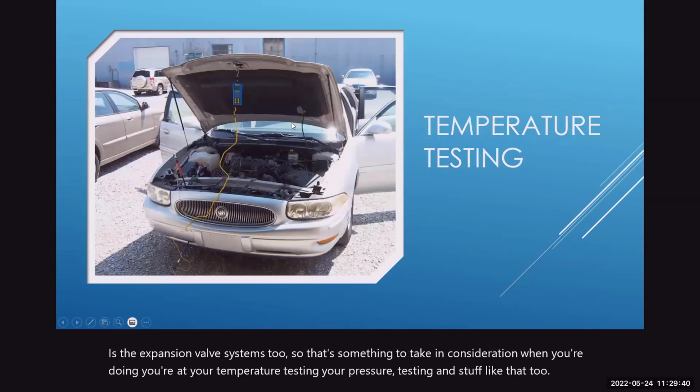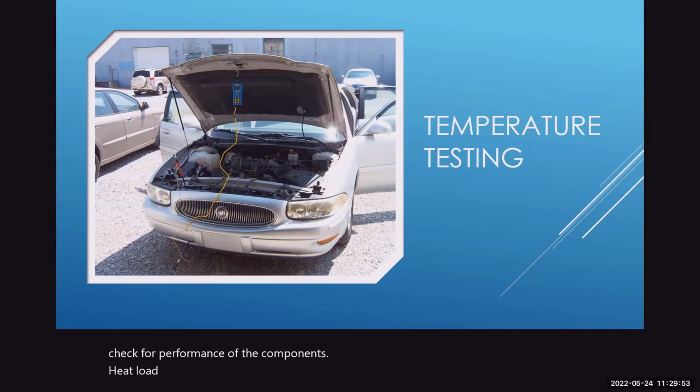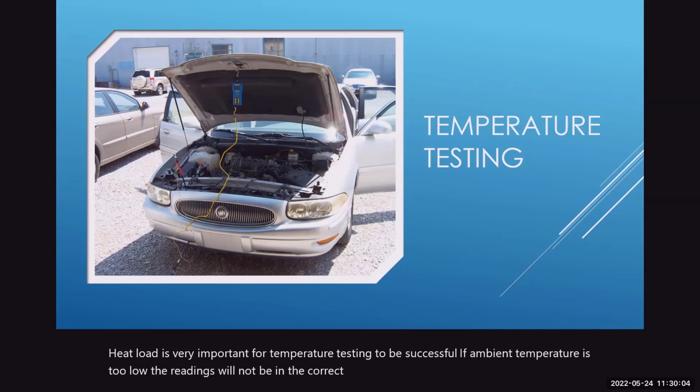All right, temperature testing is an effective way to confirm the actual charge level and to check for performance of the components. Heat load is very important for temperature testing to be successful. If ambient temperature is too low, the readings will not be in the correct range, which can lead to misdiagnosis.